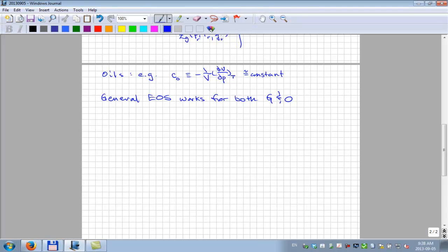And this general equation of state will be able to describe any fluid at any of these state conditions. The general equation of state that we use is typically a cubic equation of state. It doesn't have to be cubic, but this is basically the simplest form of a generalized equation of state that has been proposed and is being used actively by the industry.